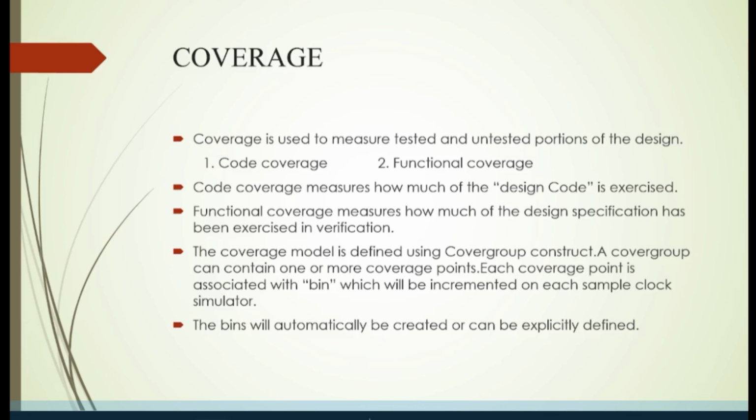Then comes the important topic, which is coverage. For example, I am designing a 3-bit adder. For a 3-bit adder, how many stimuli will you get? 2 power 3, which is 8 inputs you may receive. So coverage will check whether all these inputs are properly received, whether all 8 cases are covered or not, whether every scenario, every stimulus has gone to the DUT and the DUT is responding correctly or not.